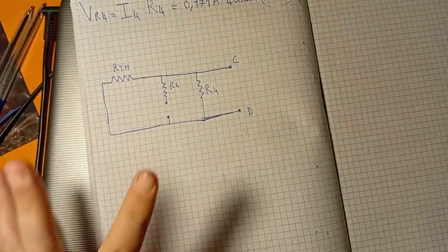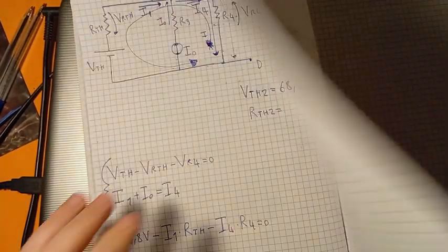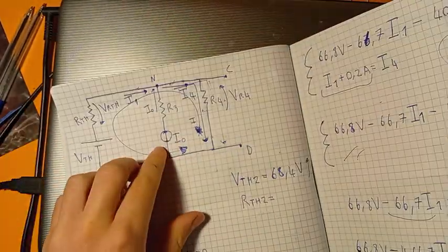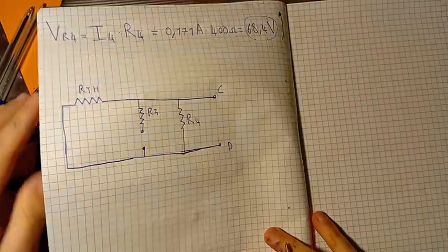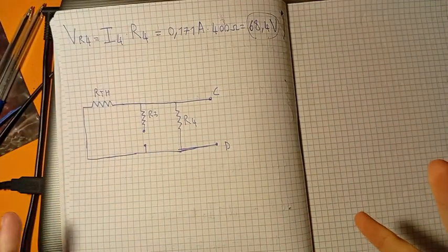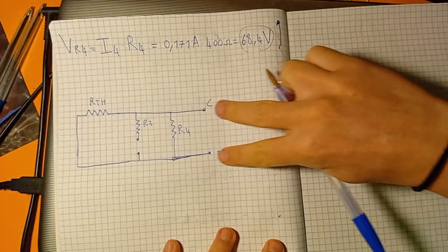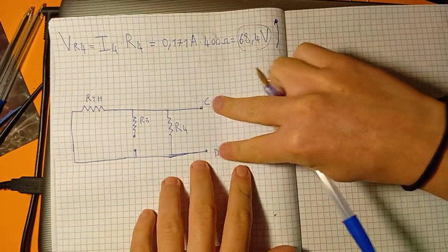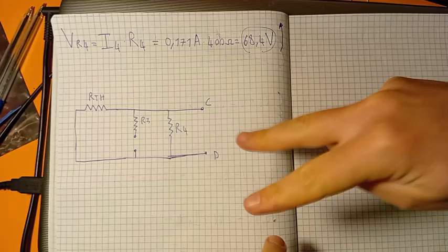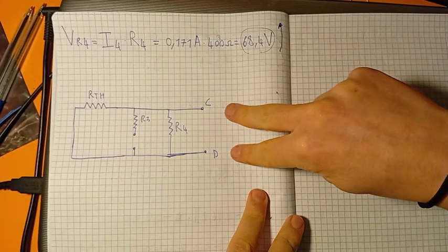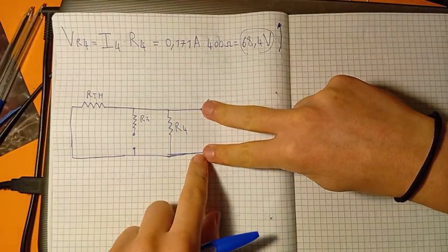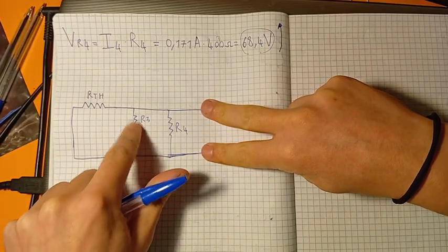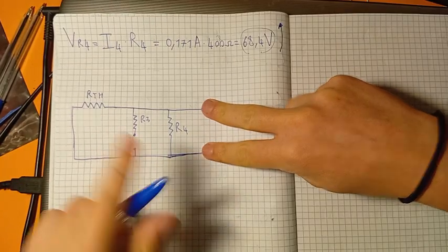So now if we have this situation, with the circuit left open, how can I calculate the total resistance seen from these 2 points? Well, if I use an instrument to measure the total resistance and I put it in these 2 points, what I see is just this and this, because this is an open circuit, so it doesn't count.